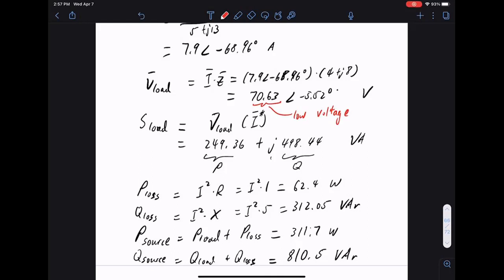what's happening is, remember, by Ohm's law, the voltage difference drives current flow, right? So I need to supply a lot of reactive power, so I need a big current. So I need a big voltage difference. Then my load voltage needs to be low, to create a large voltage difference to drive large current flow, because a lot of this current is carrying reactive power. So that means I'm suddenly facing a low voltage at my load side. And this is not great.